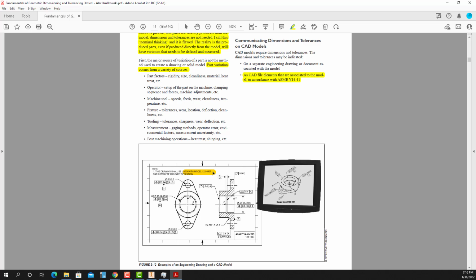And you would have all your tolerances, all your GD&T. Creo makes you put GD&T in the model, and then you show it in the drawing. Everything else is put on the drawing. So we could do that in SolidWorks and Inventor as well. But you're saying all the tolerances and everything should be in the model. Well, they better be in the model. They have to be in your dimensions. Your dimensions have to be 1, 2, or 3 places, and your tolerances will be inside there as information. I'm going to show you how we can set that up. And that's how we get to evaluate the part at the worst case.